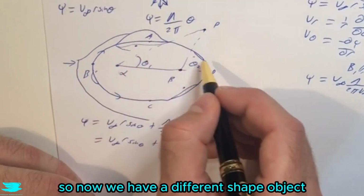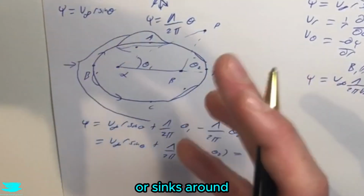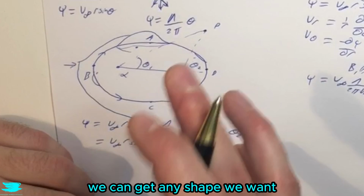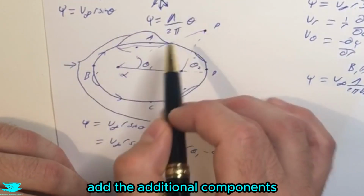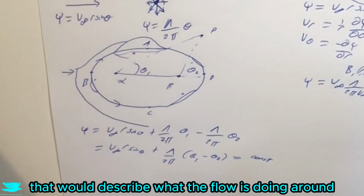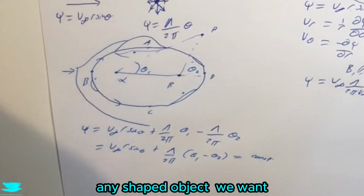So now we have a different shape object, and by putting a certain number of sources or sinks around this fundamental object, we can get any shape we want. And we just add the additional components to the stream function, and then we can get a stream function that will describe what the flow is doing around any shape of our object that we want.